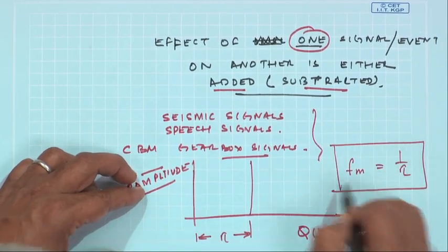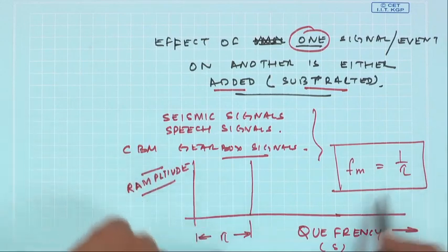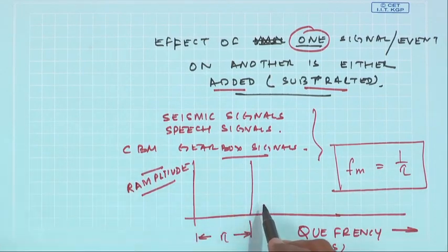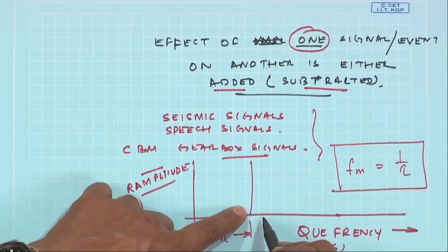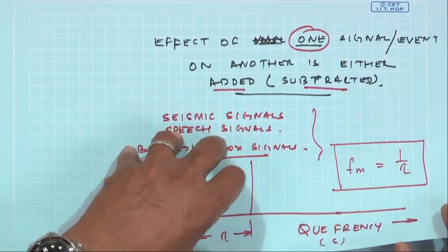Okay. So, the effects of carrier frequencies have been removed, and then I can easily identify the modulated frequency in a gearbox or in any Cepstrum signals. And we will see this with an example where we are using Cepstrum for CBM in a gearbox.